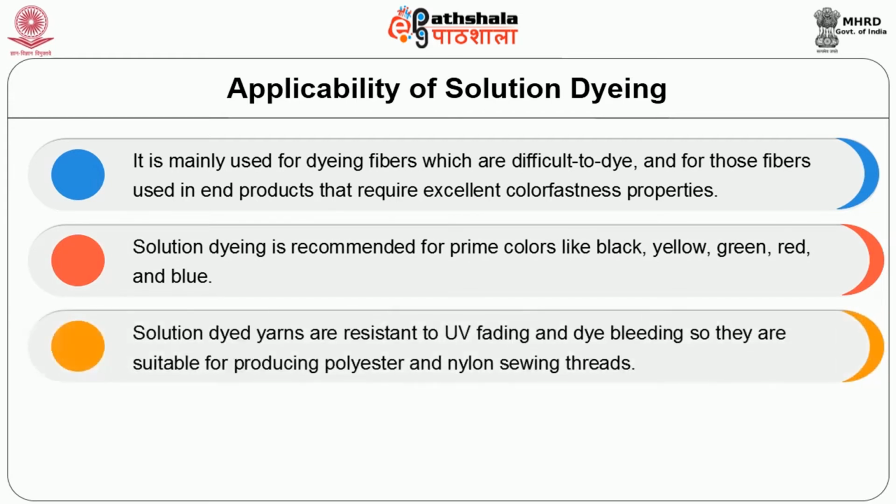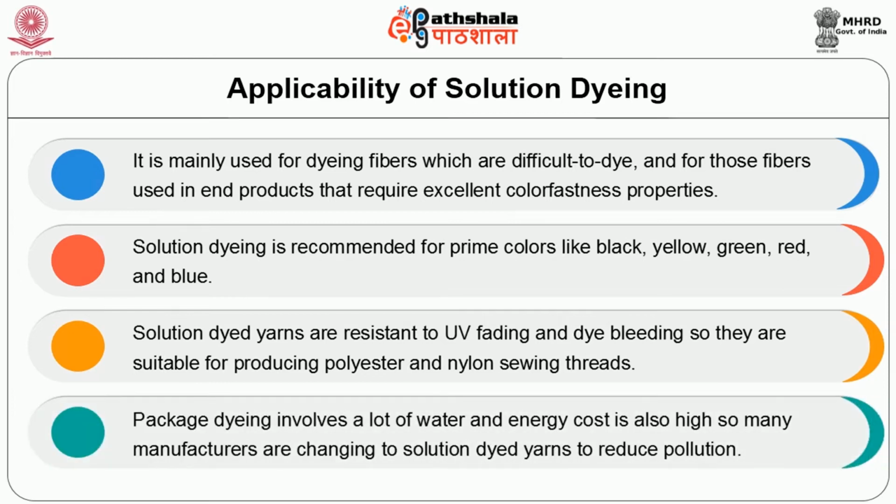Solution dyed yarns are resistant to UV fading and dye bleeding, so they are suitable for producing polyester and nylon sewing threads. Package dyeing involves a lot of water and energy, and the cost is also high, so many manufacturers are changing to solution dyed yarns to reduce pollution.